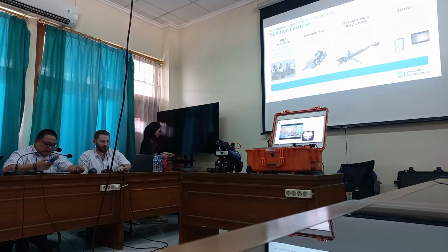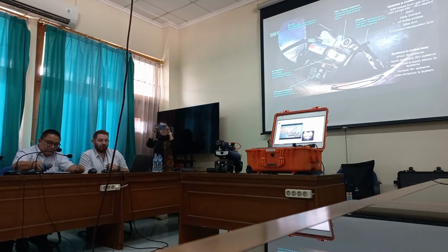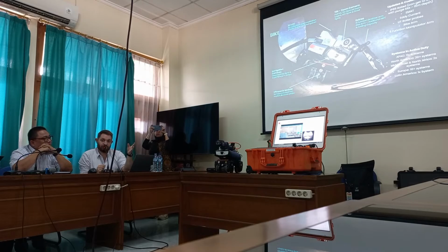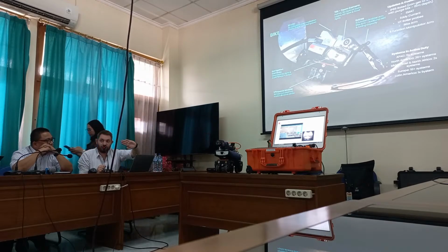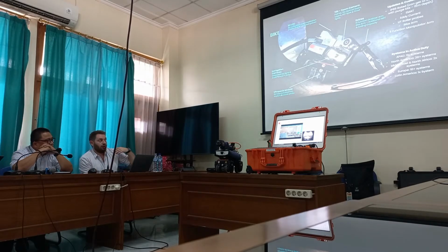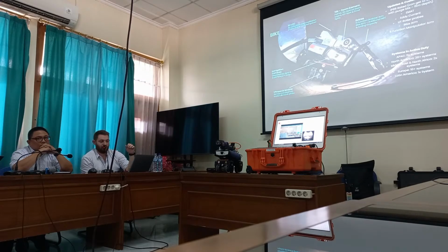As I said, the bike robot is a highly mobile inspection platform. As you would have seen in the video, it can crawl over 90-degree obstacles, both concave and vertical. We can hold up to 5 kilos upside down. We can hold more if we're flat or on the side or traveling in a vertical motion. If we're starting to go horizontally, that changes depending on the physics. Within the robot itself, the base platform, as you see here in front of us, we've got a forward-facing tilt-zoom camera. So this bit here, or the blue section on top.